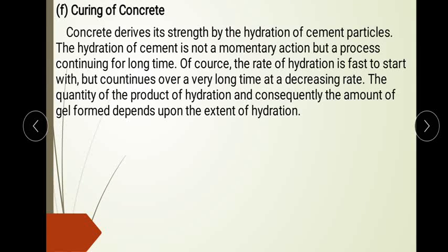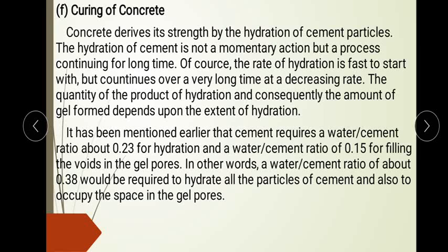Next one, curing, and this is the most important thing which we need to consider even after compacting the concrete. The hydration process is not a process for 1 day or 2 days. It is to be for a longer period. If we are unable to cure the concrete in a proper way, then definitely the concrete may collapse and it won't get its ultimate strength for longer days. For a minimum of 28 days, we need to cure any component or any kind of thing in the structure.